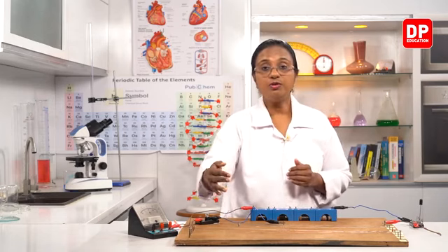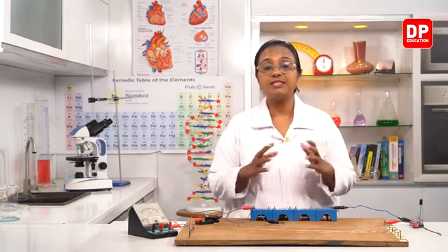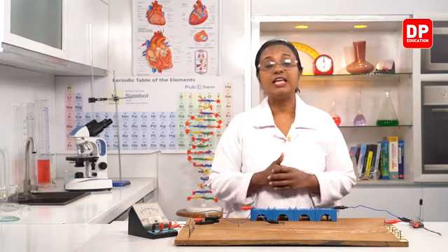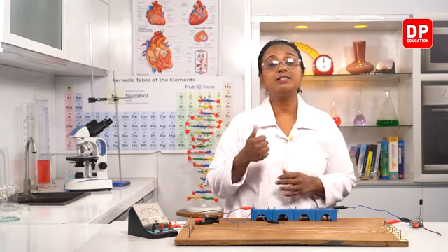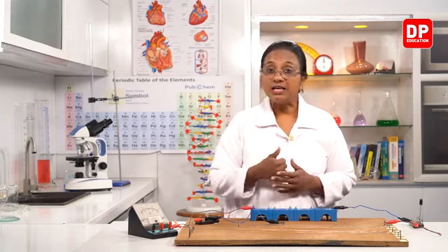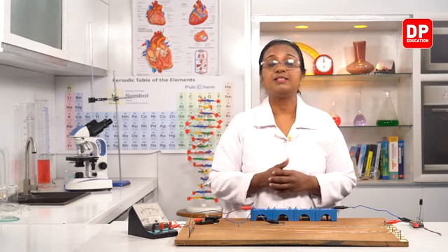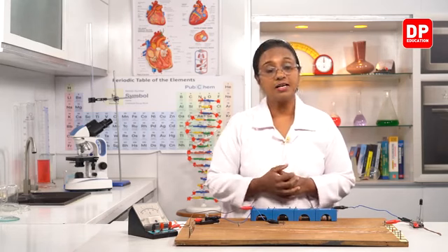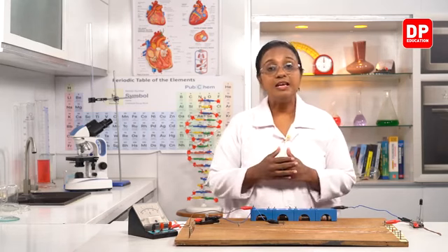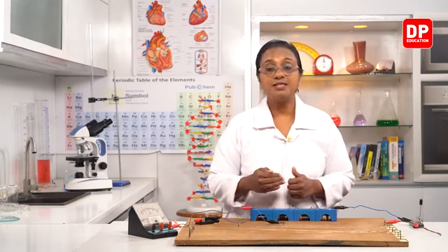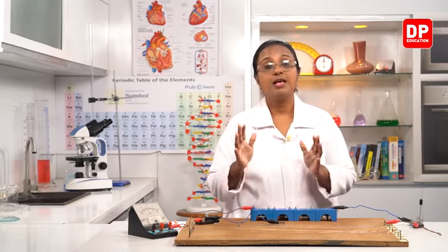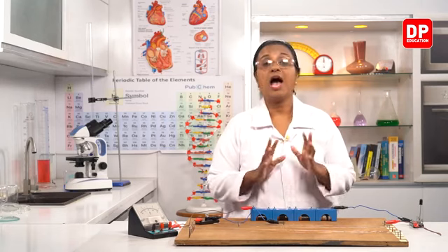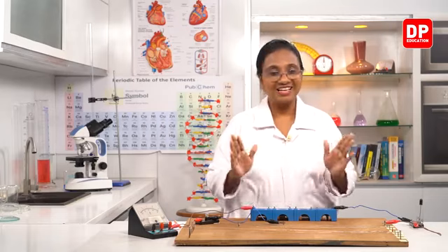So we wanted to observe the factors that affect the resistance of the conductor. When the cross-sectional area increases, the resistance decreases. Then material composition determines the resistance. That is what is related to resistivity of the conductor. And then when the length decreases, the resistance also decreases. Those are the three factors and the way they affect the resistance. I am sure you all can understand that clearly.